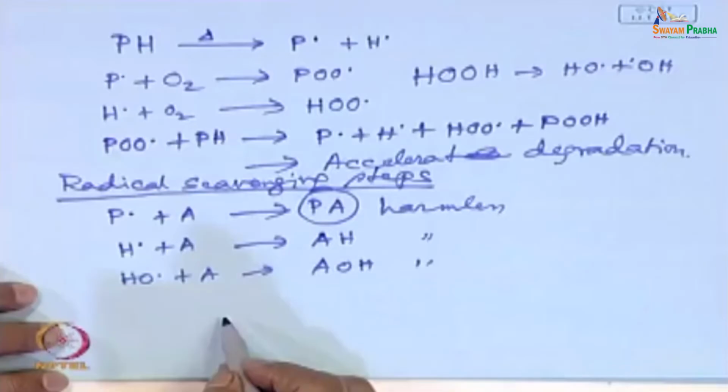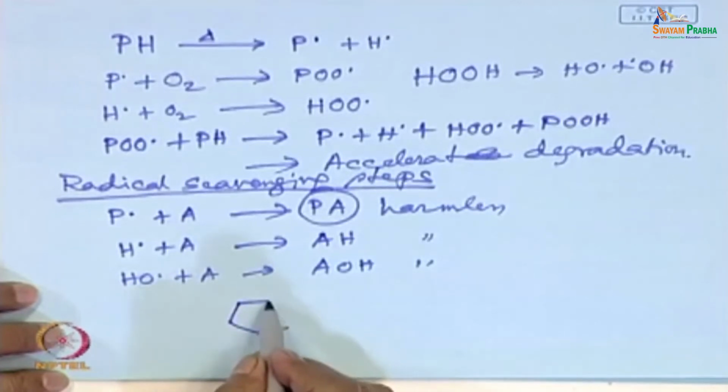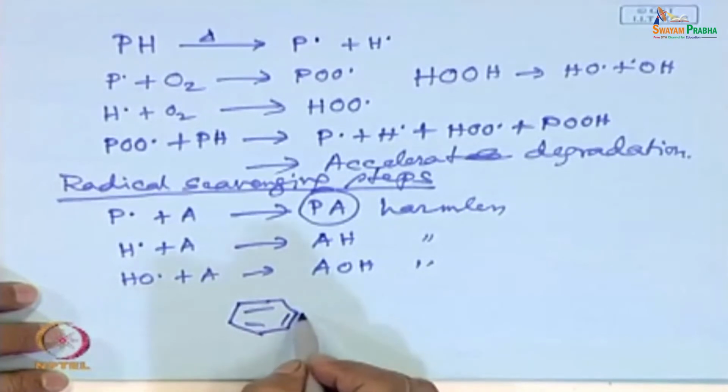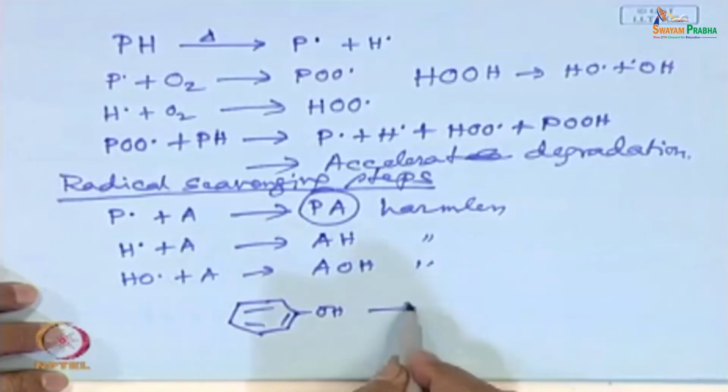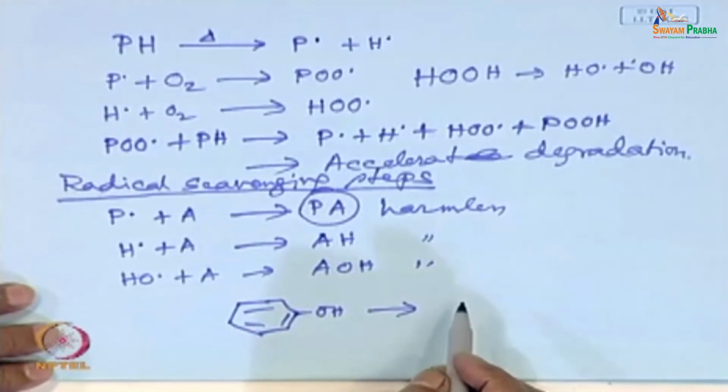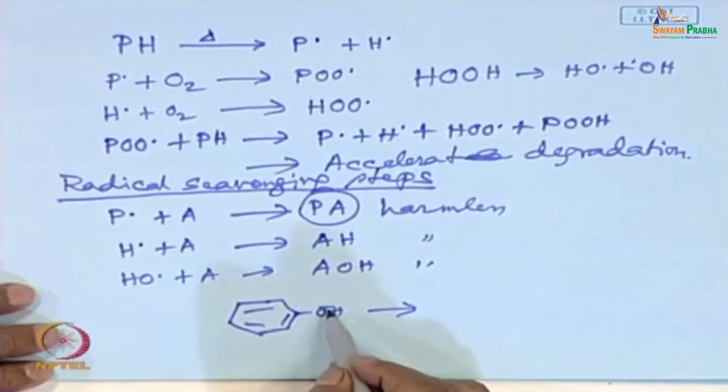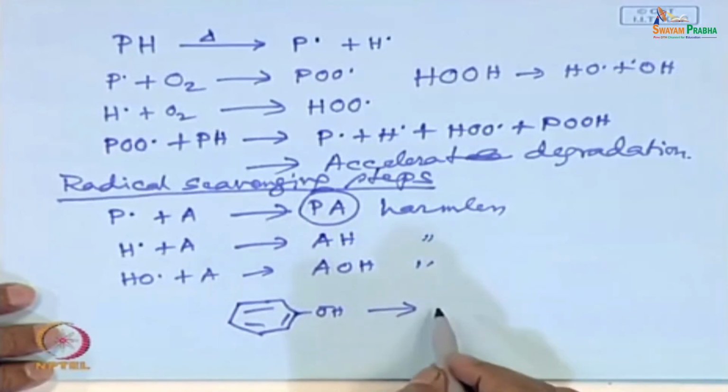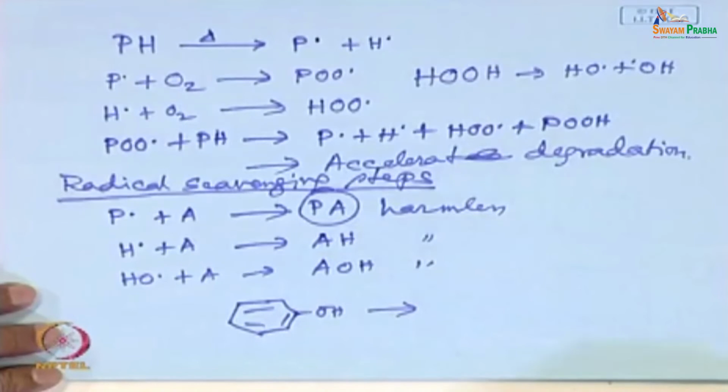These phenolic units, phenol, you know what is phenol? Phenol, now, it can form quinonic structure also. So, phenol to quinone. So, it can lead to phenoxy radical, and that phenoxy radical can give you some stable radical. That stable radical will scavenge your degrading free radicals. So, you see phenol formaldehyde products, phenol formaldehyde composites are stable, they do not degrade.